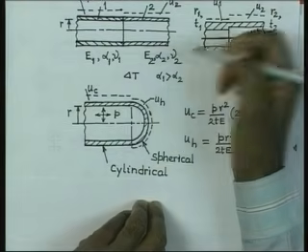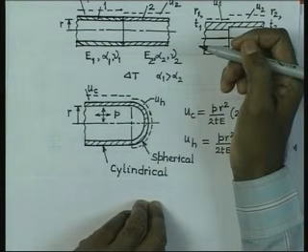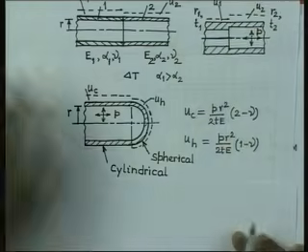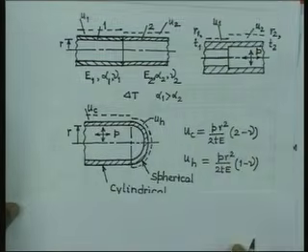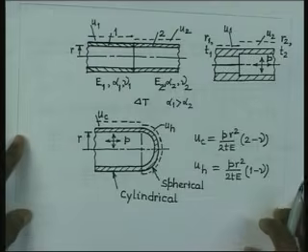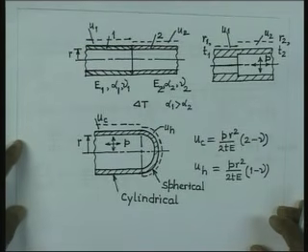So, on top of the stresses that you calculate by considering the hoop stress and axial stress, you are going to get some local stresses coming up here, and those local stresses are to be estimated. So, in all these applications you have a similarity, that you have some mismatch in the expansion of the vessel in the two segments,